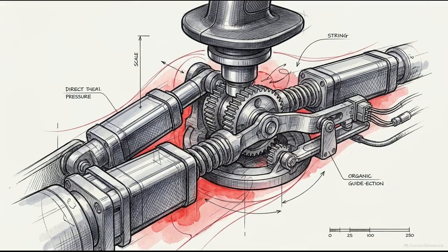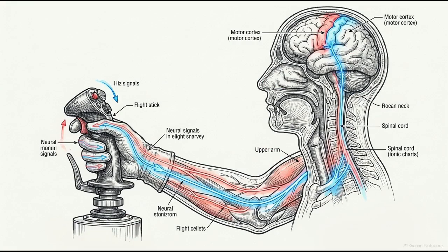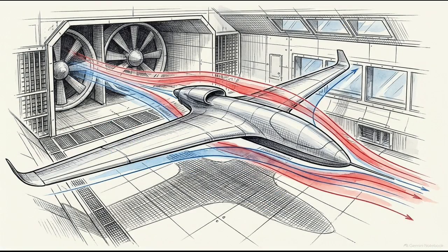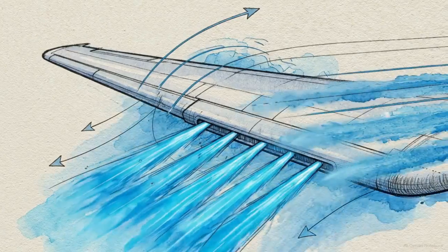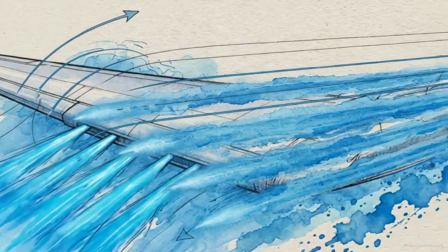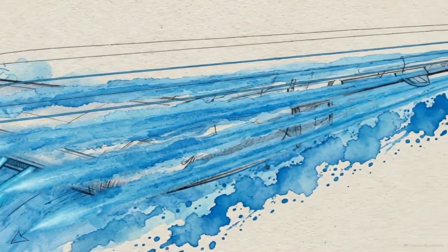Despite removing physical cables, these computers are still programmed to synthesize resistance at the pilot's stick. Tactile feedback remains a biological requirement for the human brain to maintain control touch. We are now moving toward a future of experimental flight control called active flow control. This technology replaces moving flaps with compressed air slots. Emitting small jets of air invisibly alters the flight path without any hinged surfaces.